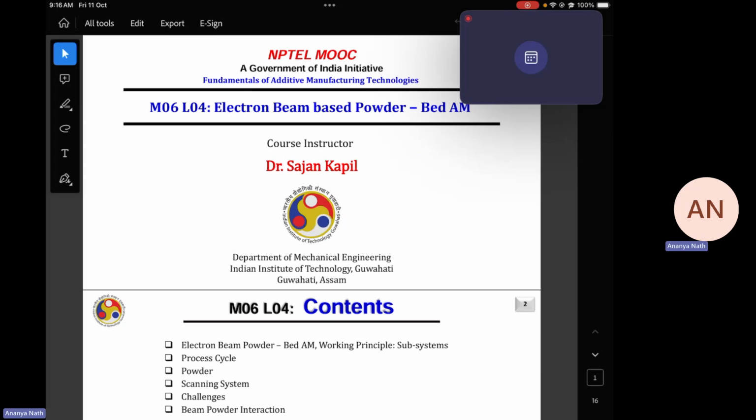In case of DED, the nozzle design is very crucial because the powder comes through the same nozzle which is also used for the laser delivery. That's why nozzle design, or cladding head as we call it, is very important. The powders meet at a certain point, which is the focus of the powder, and the laser beam also has its focus and defocus point. You have to match the defocus region of the laser and the focus point of the powder in such a way that the spot area contains the maximum number of powder particles coming from the hopper, so that they can be utilized in the melt pool and your capture efficiency will increase.